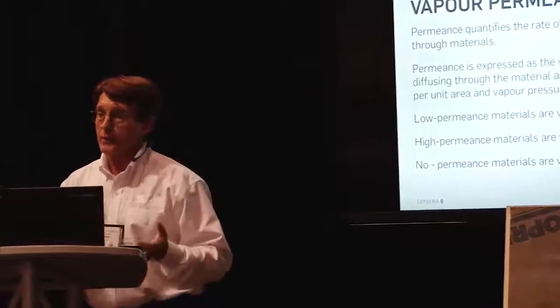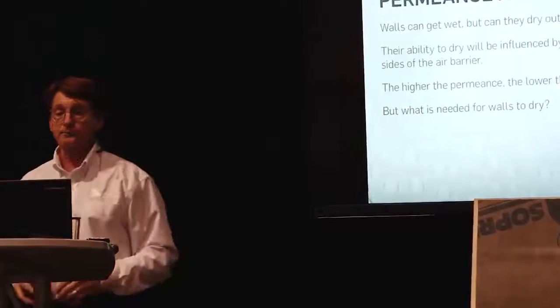And you would make these considerations on which one to use and where based, at the end of the day, on the intended use of the building. Is this a residence? Is it a student residence? Is it a hospital? Is it a swimming pool? Is it a museum where you're not worried so much about vapor diffusion? In a swimming pool and a museum, you're worried more about maintaining a certain vapor load. So in those cases, you would look at materials that have no permeance.